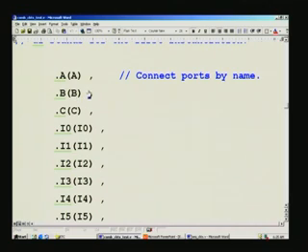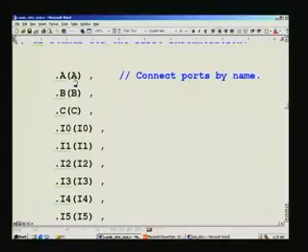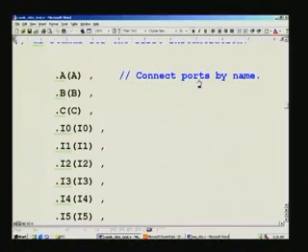See, order matters because you do not know whether it is an input or an output. As I said, you can have a free mix of inputs and outputs, right. Unless you maintain the very same order, how will the tool know? You can have very many combinations. You can put one thing there and totally radically change from that combination. How does the tool know? It does not have that much intelligence. You have to inject that intelligence, right. So, the way to do this is what is called connect ports by name, right.